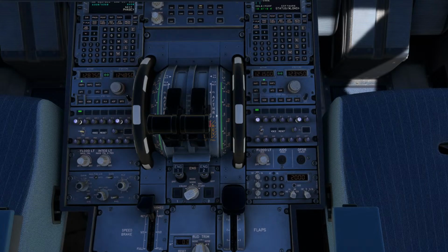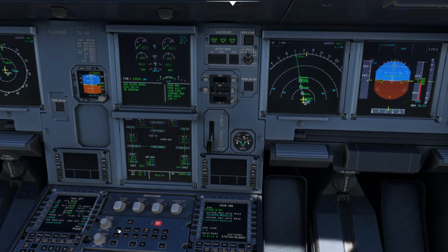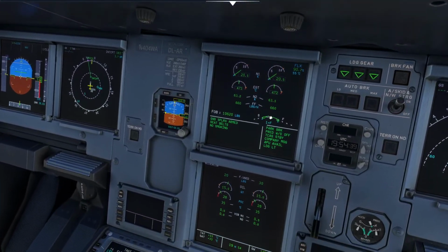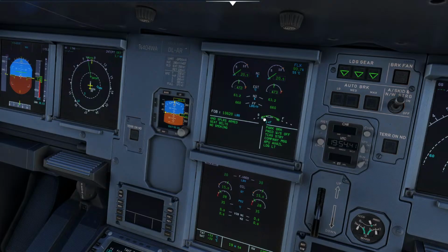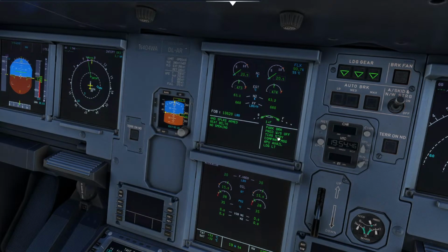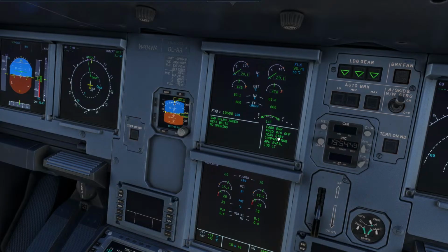Yeah, look at that. Nice. That's pretty sweet. I'm excited. Oh, it's fun. You're gonna love it. All right, so that's cool. And then we can go back to normal on the ignition switch. We can arm the speed brake, flaps one, and we can go back to the engine page here. And there's your flap indicator. The front of this is the slats. So S is slats, F is flaps. So 1 plus F means you're getting slats along with the flaps.